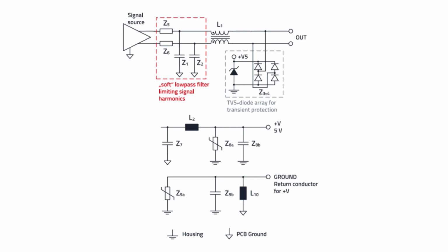First, determination of the L1. This is an inductor with high impedance for common mode noise. It allows for differential signals to pass with minimal attenuation in the relevant signal frequency range. L1 selection is crucial in terms of differential as well as common mode impedance needs. To ensure proper signal transmission, choke L1 should be selected according to the interface type and, of course, the datasheet information, taking these parameters into account.